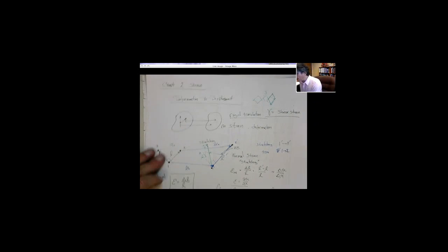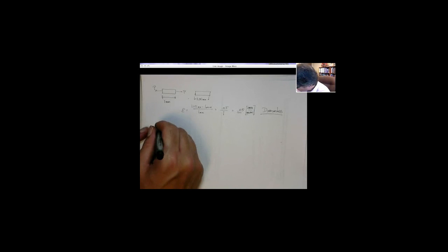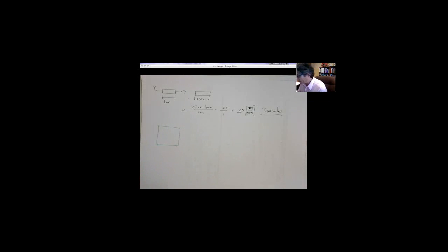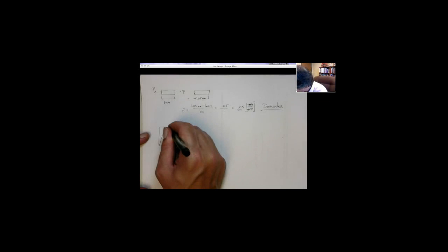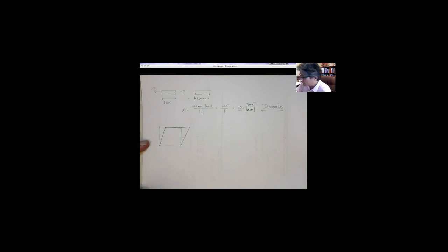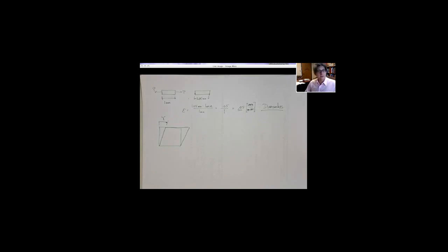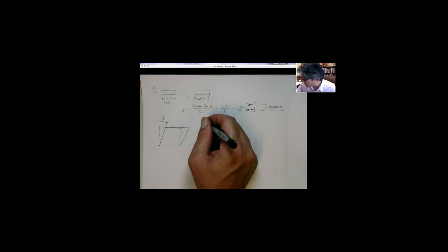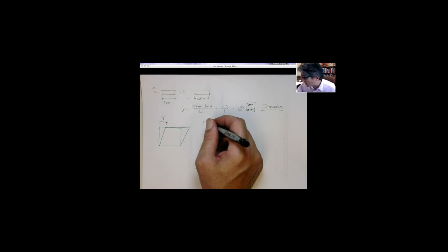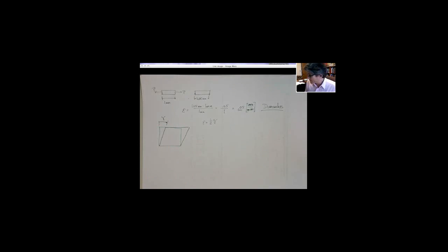All right. So if I draw it a little better, let's get its own page going. So the shearing process, let's say we initially have a block that looks like this, and a shear type of deformation is one that might look like this. So this angle here is the engineering shear strain. This is in contrast to another thing called the shear strain, which is the real tensorial quantity, and that turns out to be 1/2 gamma. But we won't use that often in this class. Mostly we're using gamma, which is the angle change.